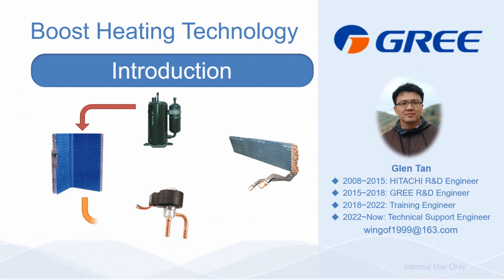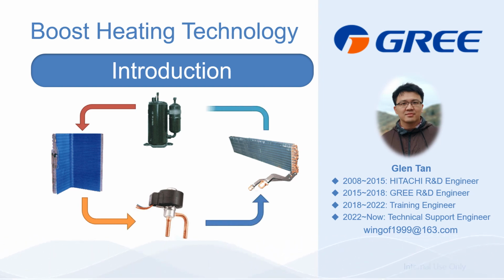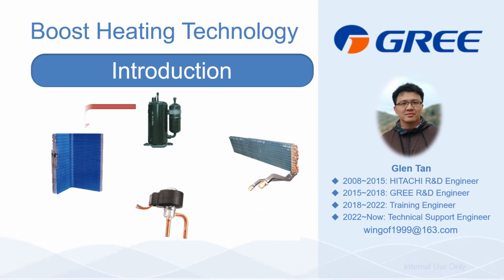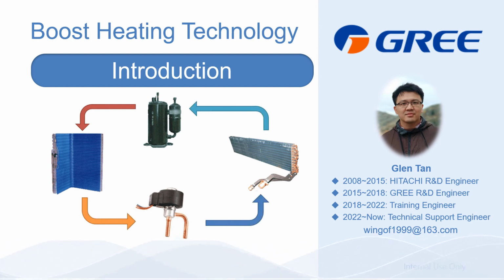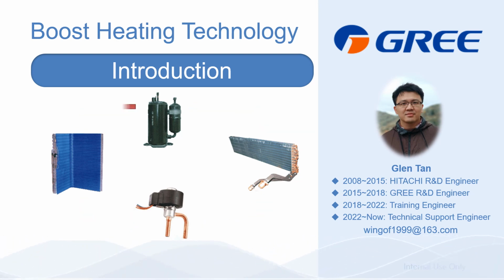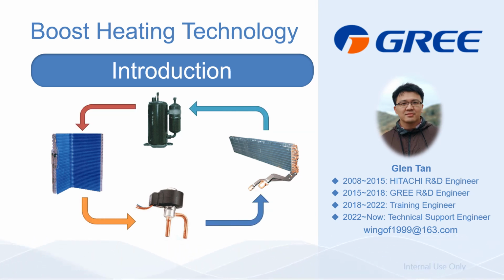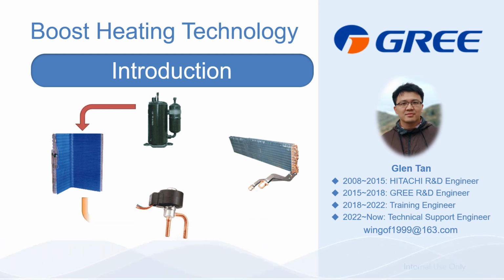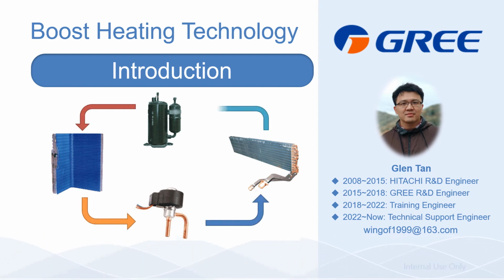This time, I'm going to talk about boost heating technology. This sharing is about the pros and cons for the boost heating technology. As I'm still working at GREE, I'm going to review which products mainly in the North American market apply this kind of technology. And also during this sharing, I will show you how the refrigerant flows in the cycles.